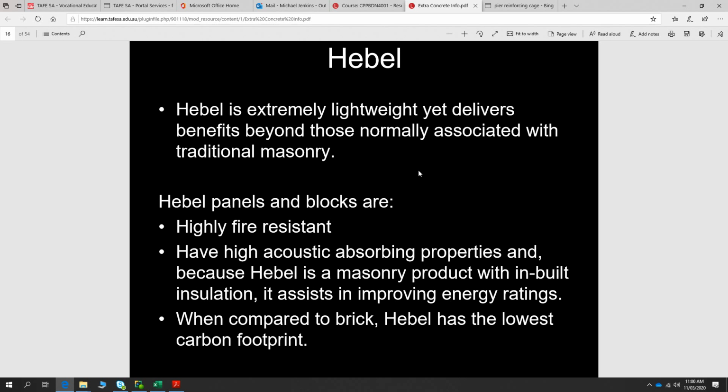So with that Hebel sample that I passed around there, you'll notice there's steel fibres in that. That gives it a lot of strength. If that Hebel didn't have those steel fibres in there, then you wouldn't be able to use it as a flooring system to span between supports a long distance away. And also in that concrete core sample, there's steel bars going through that as well.